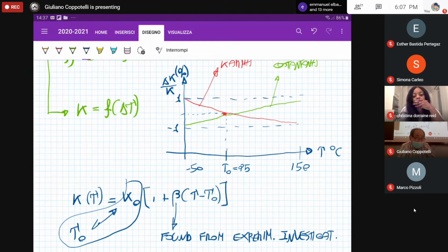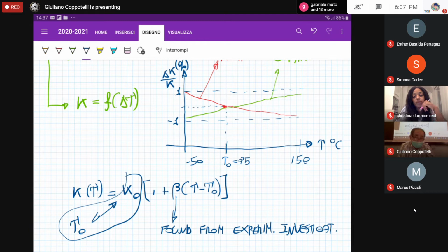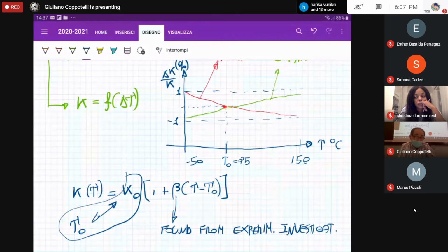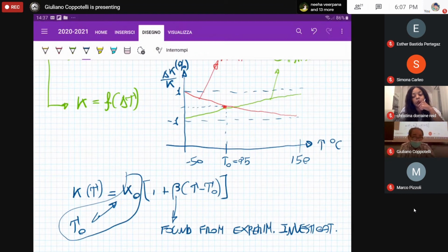Okay, so if I'm using a strain gauge for, let's say, room temperature, then 25 degrees is okay. This trend could be accepted. But if you are willing to use your strain gauge at, let's say, 1000 degrees Celsius, to mimic the operating condition of a jet engine, then you have to ask the manufacturer for that trend, but close to the operating temperature of about 1000 degrees Celsius.